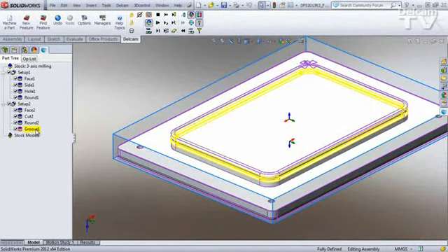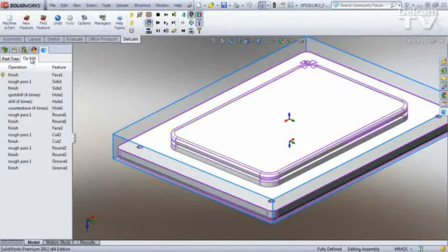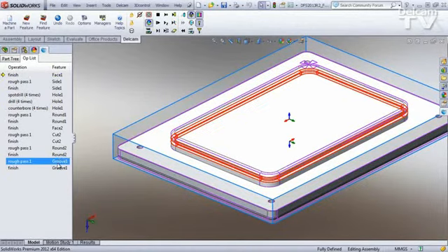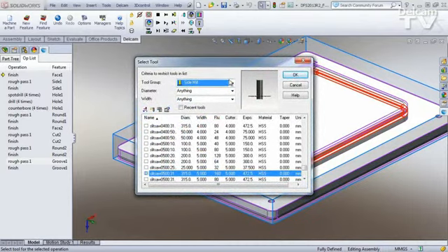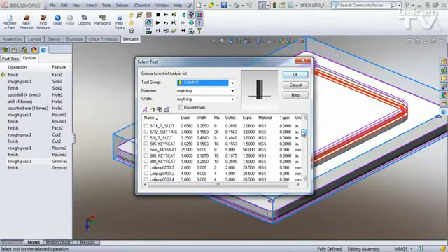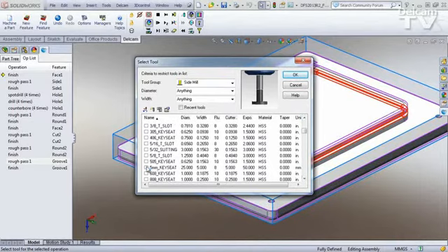Okay, so there's groove 1 down here. I'm going to run to the op list, get that tool that I imported. So I'm going to click and go select a tool. Got the side mills here. They pick by default. I don't want to use big side mill. I don't have room for that arbor or that nut or whatever's underneath that slitting saw. It's going to hit my part. So I want to use a fairly small, this 5 millimeter, if I can find it, key seat right there.